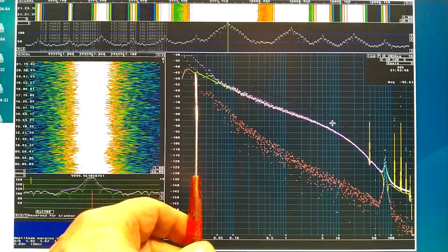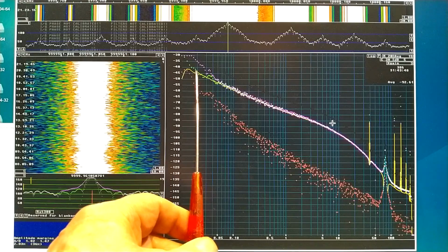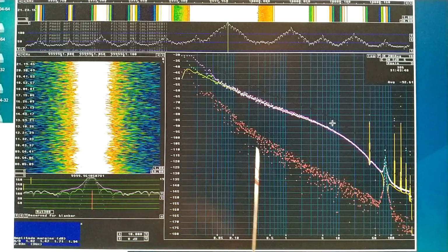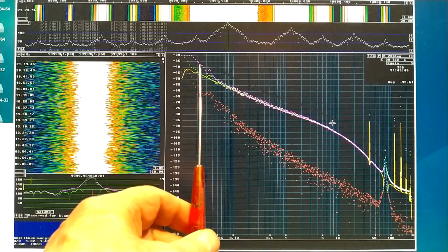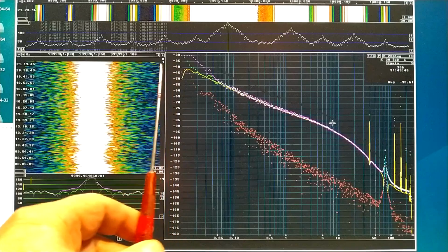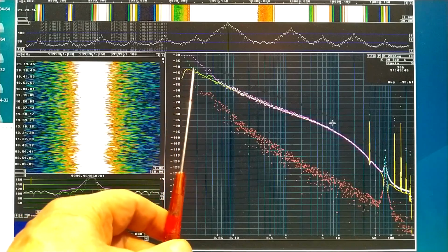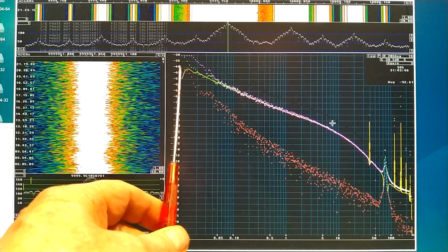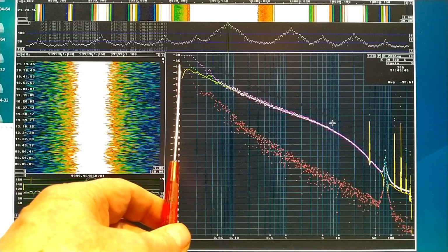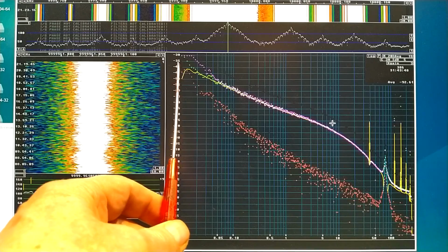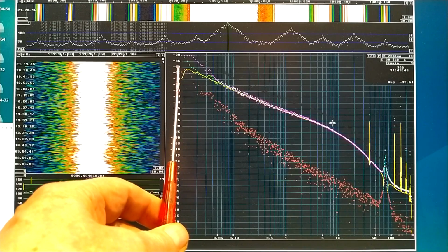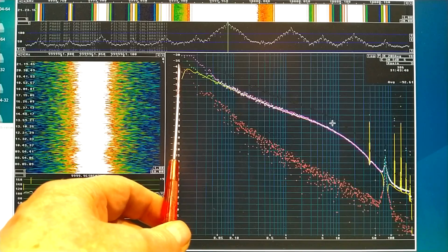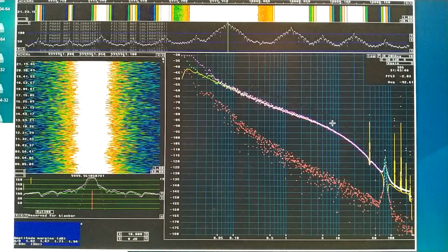Means I have uncorrelated low noise oscillators down here somewhere from channel 1 and channel 2, but below 0.02 Hertz both channels would have the rubidium oscillator, so they would be the same, so correlation would not help, but both of them would be of rubidium quality, which surely would be better than any crystal oscillator I could build.